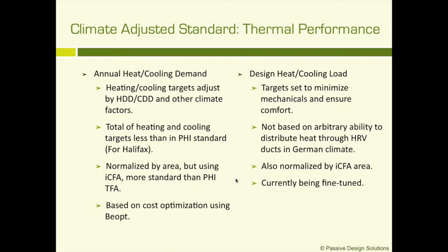The area is calculated using ICFA. This is more standard than the German TFA. It's an ASHRAE-defined international conditioned floor area. In some designs you get more square footage to work with for your energy budget because it counts stairways and it counts all spaces, I believe, above 6 feet.